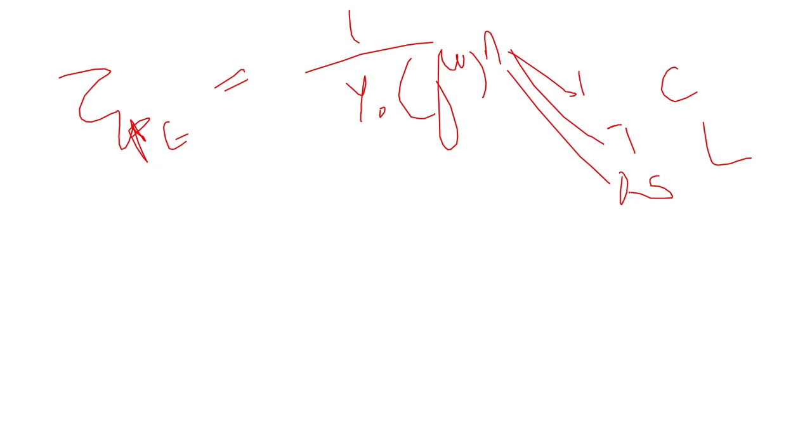Then cation vacancy generation. Cases can be given and you might be asked to identify the case. Cation vacancy generation is where you have the movement of a cation from the film to the electrolyte, from the film solution interface, and that results in a cation vacancy in the film. Then you saw cation vacancy consumption, where the cation vacancy diffuses through the film and arrives at the metal film interface, where it gets consumed.